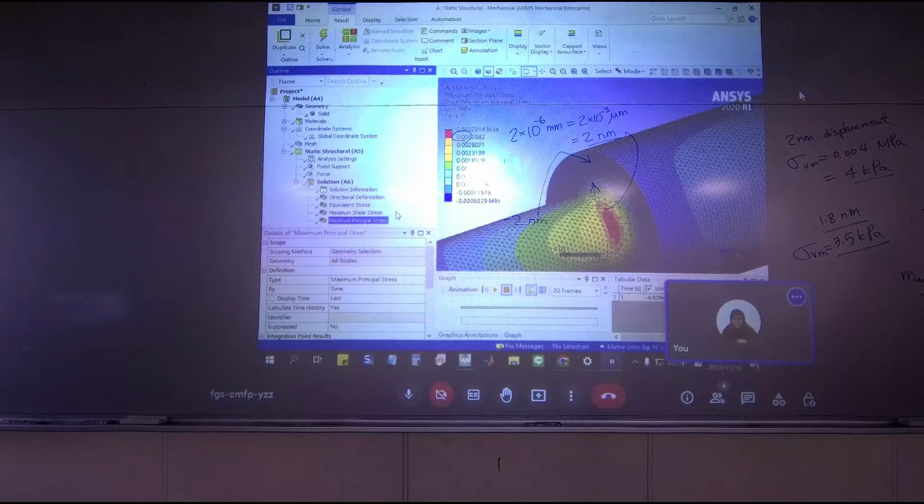Because the von Mises stress is more conservative. Oh no, more liberal. More aggressive. Yes. Remember, when we work on the model, there's a model like this. Thank you for your answer. This is our maximum shear stress model, and this is for the plane stress problem.